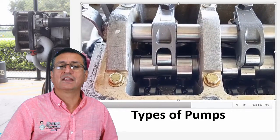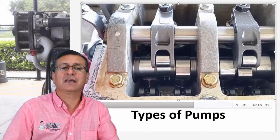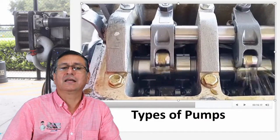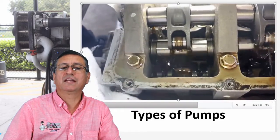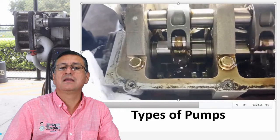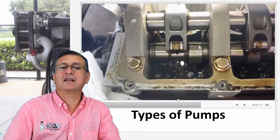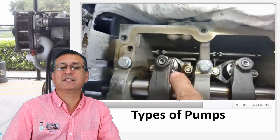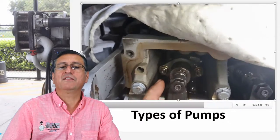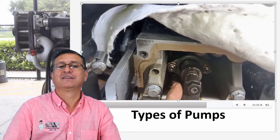Right now I am going to start the engine to show you how that engine operates. That's the lubrication. Exactly, the rocker arm in the middle. Right now the engine is running. The valves here, and the rocker arm for the fuel injector over there. On the other end of the rocker arm, the injector is compressed, and the injector sprays the fuel each time the piston finishes the compression stroke.